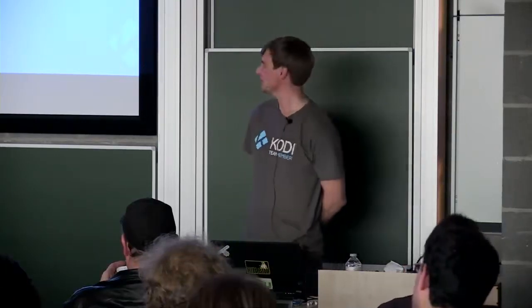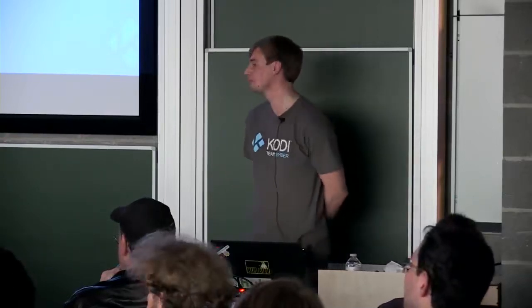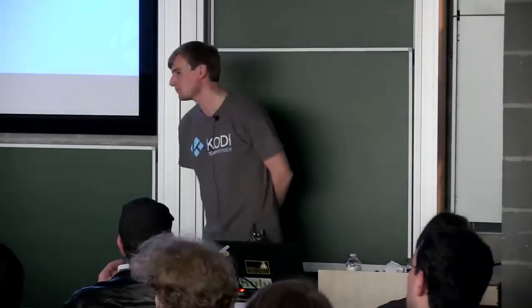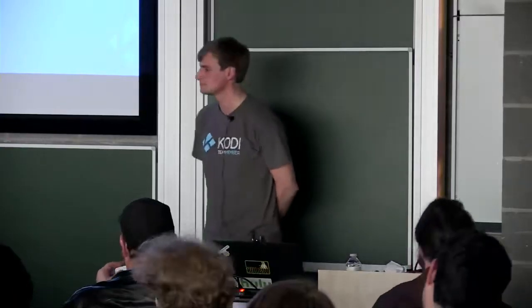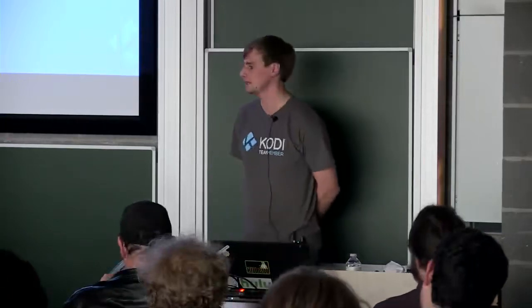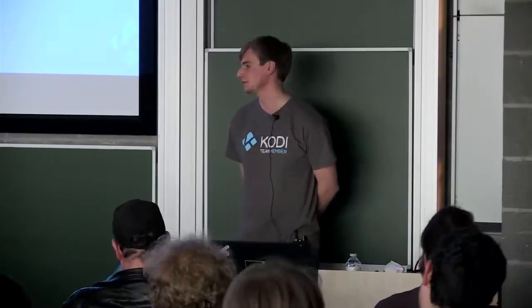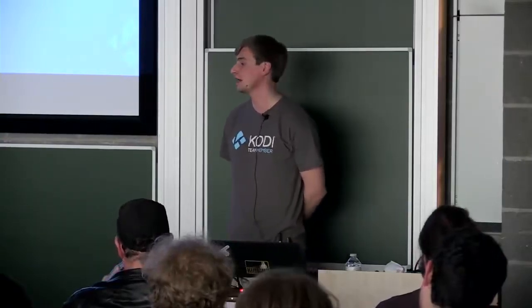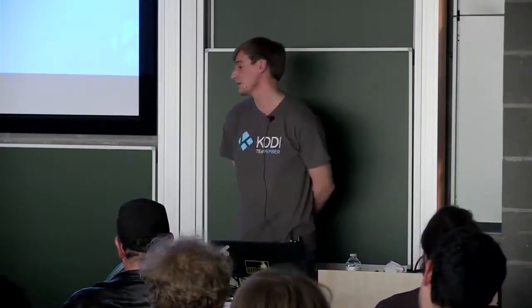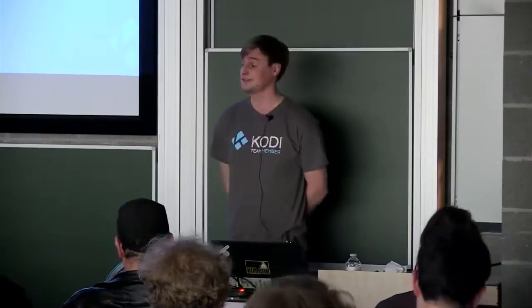Any other questions, like just in general about Kodi or anything? You mentioned the IMX6 support is great, and then IMX8 is coming. Is it going to be a big delta, because everything seems to be mainline? Unfortunately, there's quite a bit of work still to do for IMX8, as far as I know. The hardware video decoder is a completely different chipset, so the V4L2 driver needs to be completely implemented from scratch. Apparently, there's great documentation for the IMX8 chip, though, so hopefully it'll be done in a relatively quick time period.